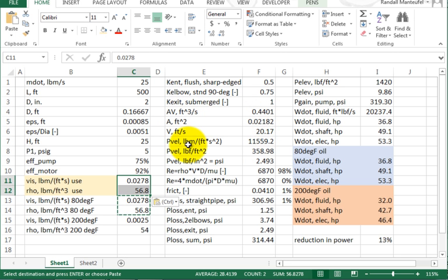The velocity, notice I leave this because I'm trying to help you here avoid errors. The velocity pressure in these funny units, because if you just throw, hey, it's just 1/2 rho v squared, you're going to get pound mass per foot second squared. But then you convert that to pound force per foot squared using a conversion factor. Then you convert it to PSI, 144 inches squared per foot squared. And now you can almost read this. Oh, it's 2.5 PSI. That's the velocity pressure.